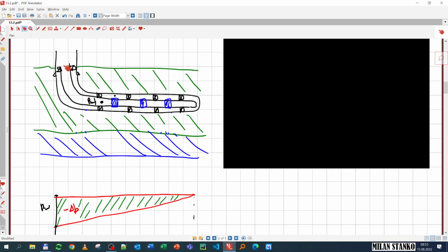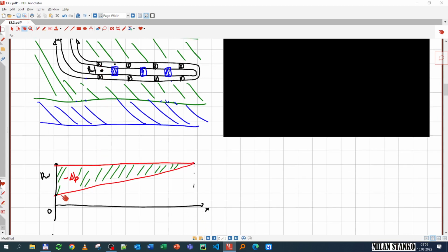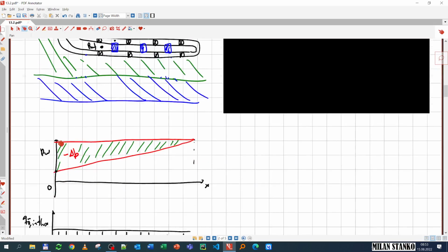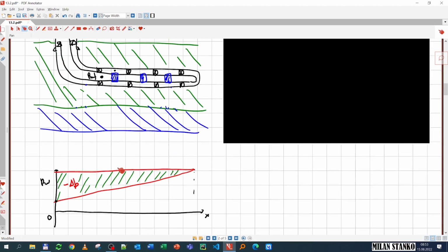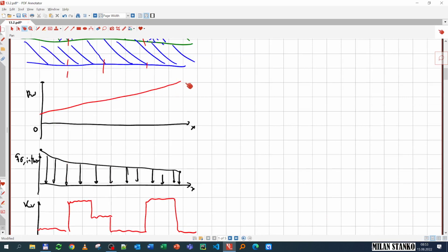For that I have run a liner, then I have put packers to create several sections. I have just put 3, but I might have quite a few in a long horizontal wellbore, and then I call this last point the flowing bottom hole pressure. So essentially the strategy is, remember that our pressure distribution before was very varying along the wellbore. What we want to do is put all of them at the same level, at the same pressure. And the easiest is to lower this down.